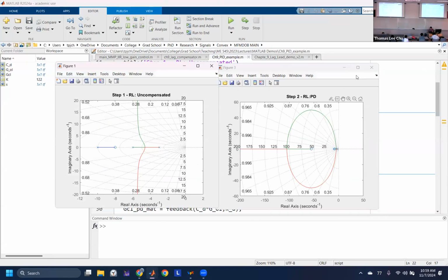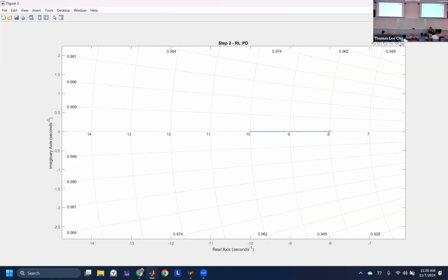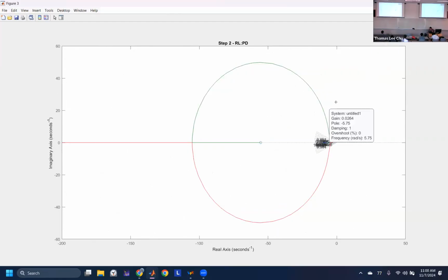And then we're seeing if our root locus passes through negative 8.13 plus 15, which is roughly there. Yeah, see, so we got it. So negative 8.14 plus 15.8j, which has a gain of 5.35. Now, if you look closely, we do have a third pole right there. It's really close. Oh no.